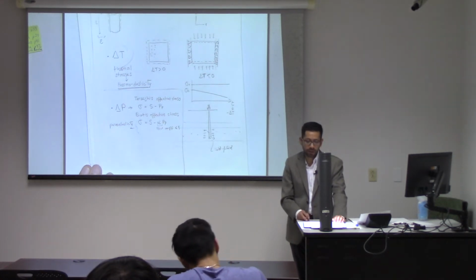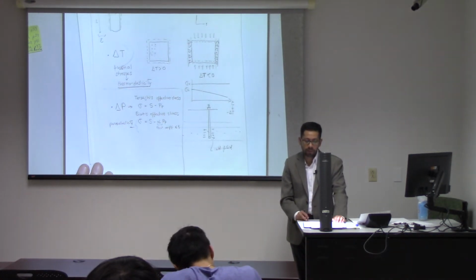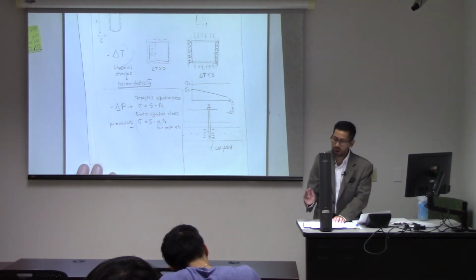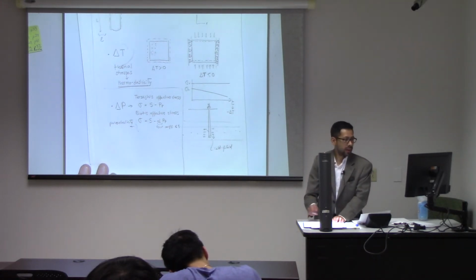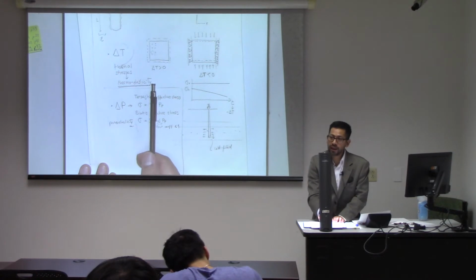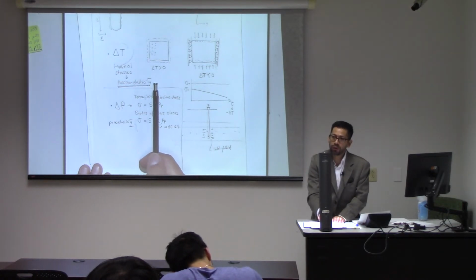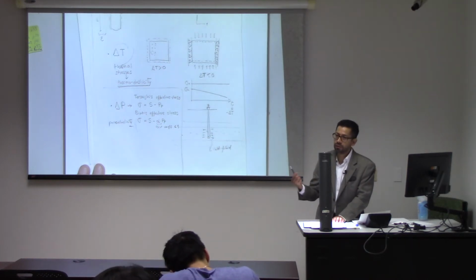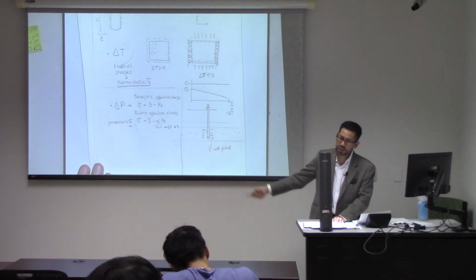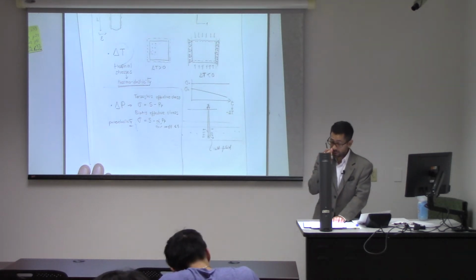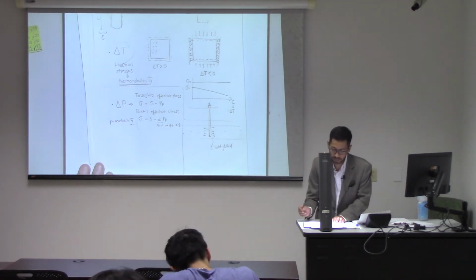There are some other very important things that we have to cover. So we'll not go through the theory of poro-elasticity. Thermo-elasticity we're going to see later on when we talk about wellbore failure. Because as you may imagine, if you're dealing with a cold fluid, that's going to favor rock shrinkage around the wellbore, and that's going to favor tensile stress.